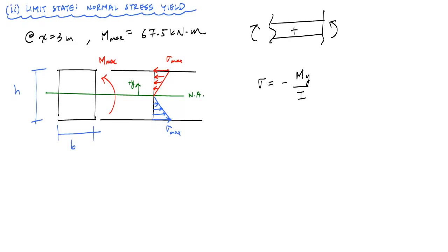Now, in more complex beam designs where you have maybe an I-shaped cross section, you have to actually consider things like buckling in the compression zone and other kinds of limit states, like a plastic hinge if you're doing steel design. But we're not going to go there, right? We're just going to keep everything linear elastic, and first yielding is going to be considered our failure, or our limit state for this simply supported beam. And so our basic design relationship is as follows.